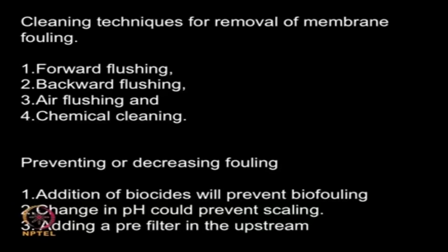So if the salts start precipitating out, you are going to have a lot of fouling. Another approach, we can add a pre-filter, that means we can have another filtration setup which can remove most of the dissolved solids, or if there are suspended solids we can have a simple sieving filter which will remove all the suspended solids. So we can remove most of this type of solids by incorporating a pre-filter in the process.